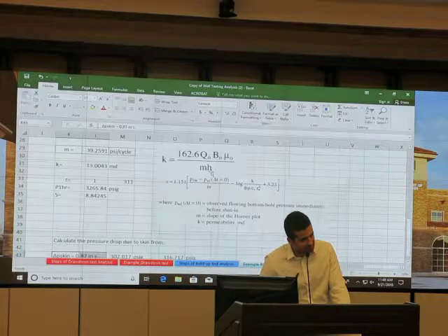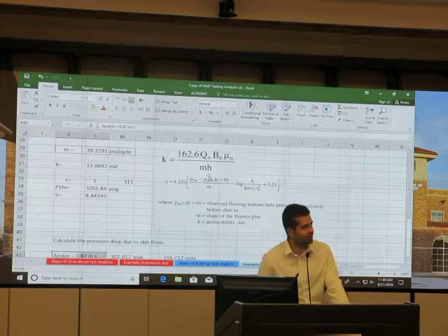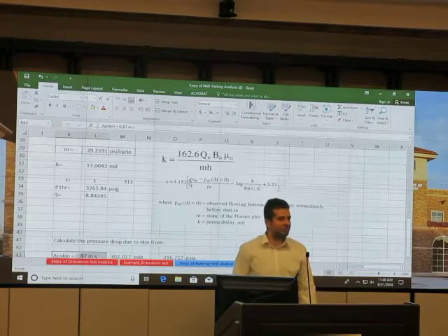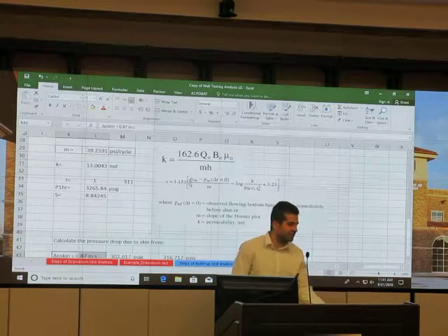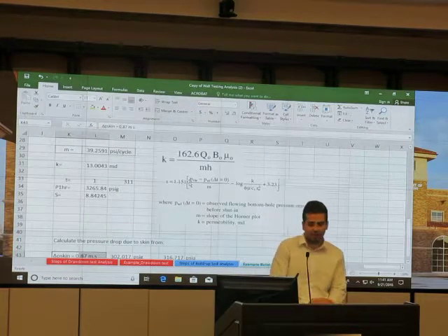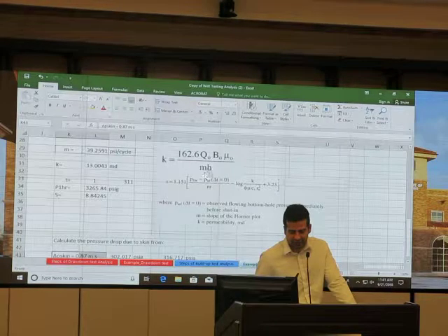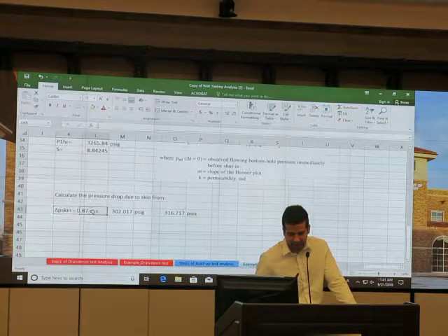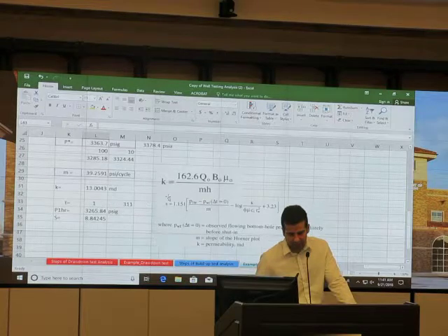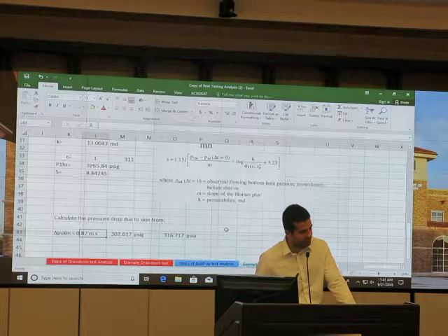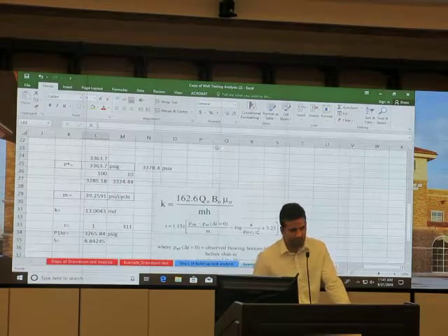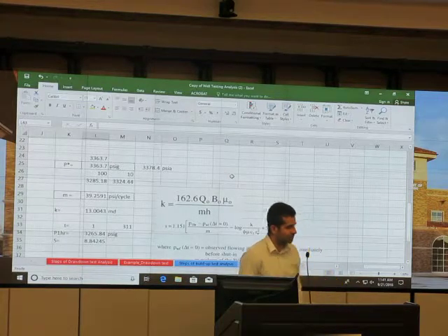Yes. Okay, it's right. So the skin factor does not care if it is steady state or unsteady state. Based on the given production rate, viscosity, formation volume factor, and your permeability k, m is always constant. Then you can get the h. Does it make sense? Okay.